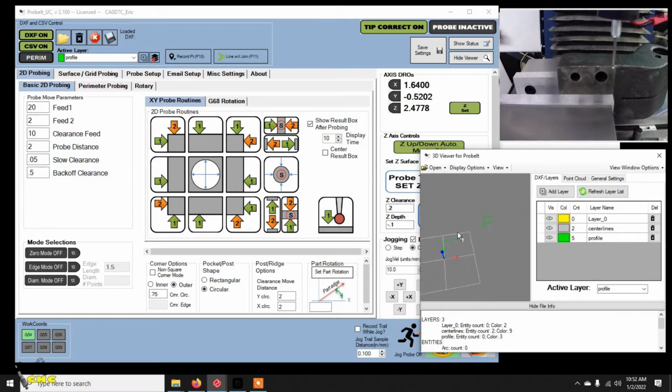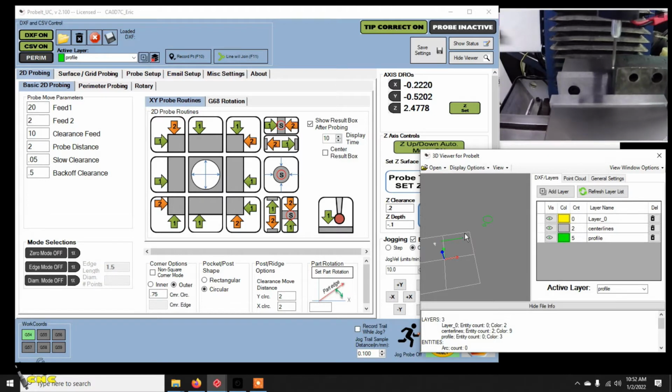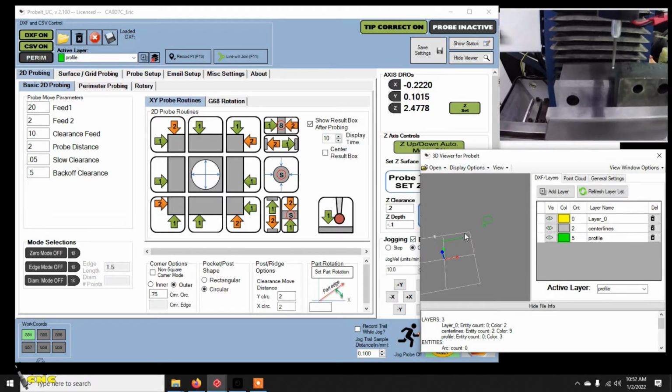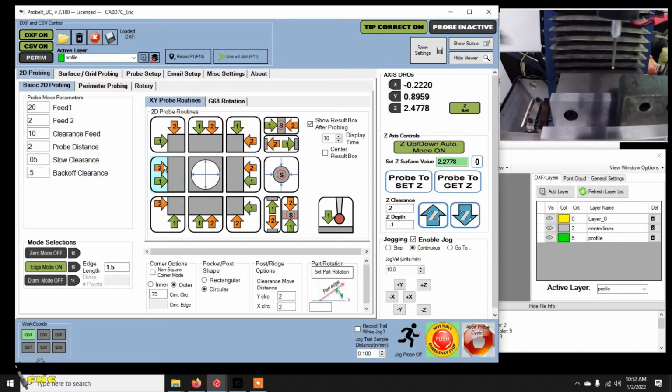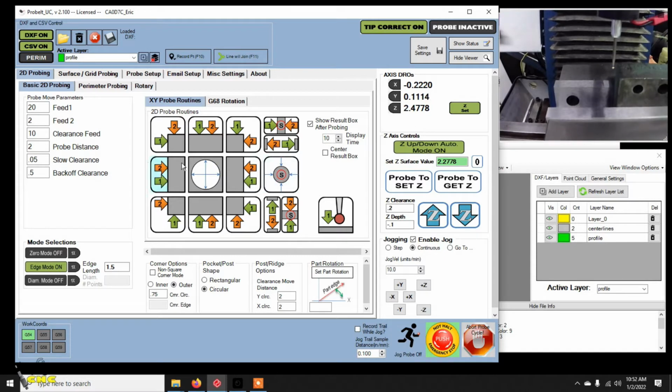If we go back and look at what we got, we just dropped a line there where we did that probe. So let's do an X probe on the edge. Again, one will be at this and then it'll travel upwards in Y, and it looks like a length of a little under an inch. So I'll come back here, put our edge length at 0.8, and run that.